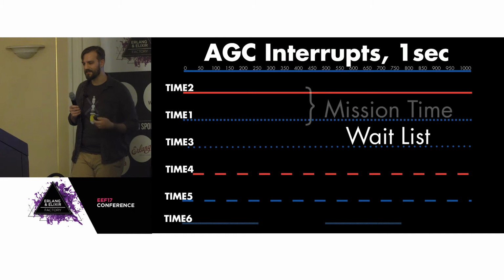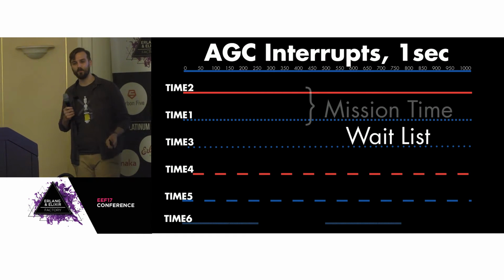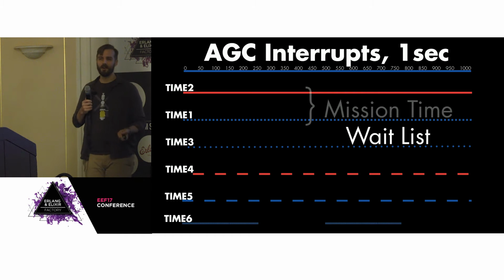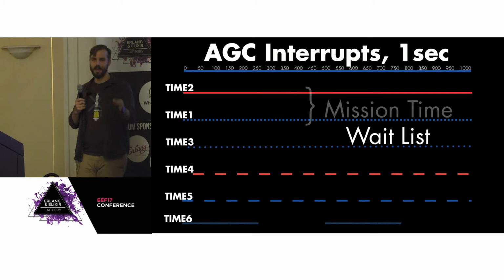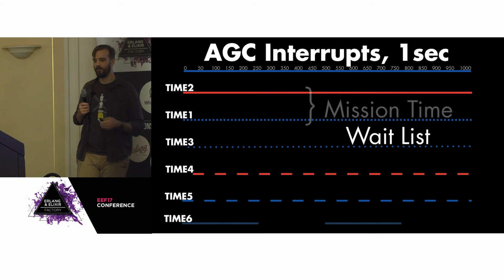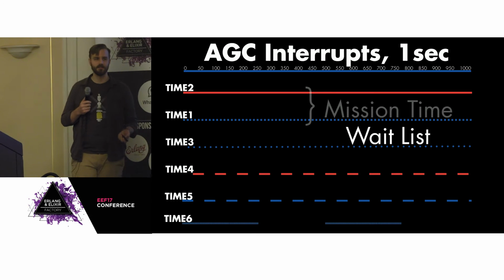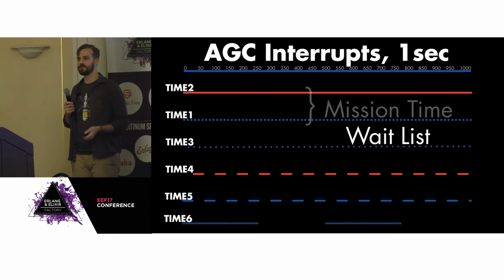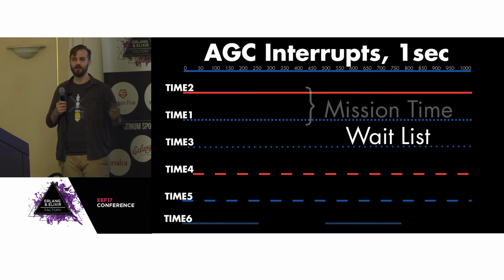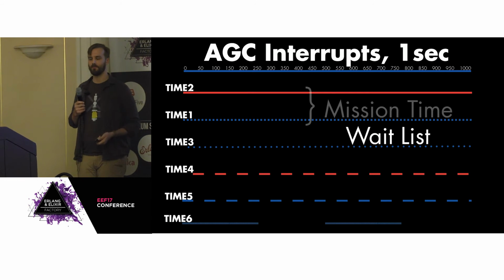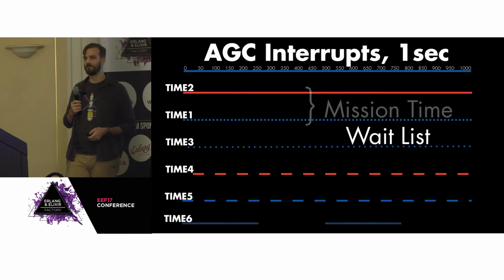So the second type of time is the wait list. The operating environment of the Apollo guidance computer was written in machine language with abstraction built on top of that. The wait list are simply low-level routines that the computer needs to do. It periodically needs to listen to buses. It periodically needs to swap some bits of memory so that you can receive command telemetry from the ground. And that's what the wait list does. And it's written in the lowest, most hateful machine language available to the programmer.